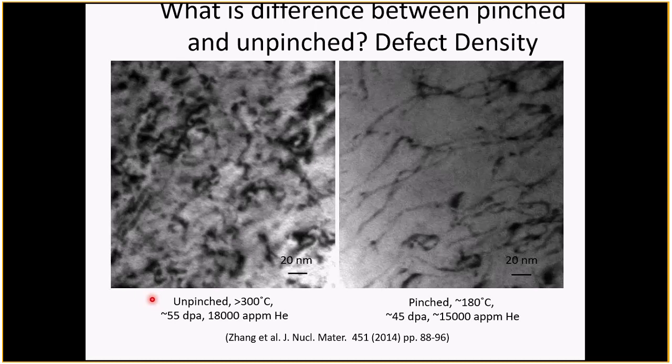You remember in the lecture I gave about diffraction and use of TEM and X-ray diffraction to characterize the microstructure of materials. Well, here's using TEM imaging, TEM diffraction contrast now, to look at the dislocation structure inside the material. Now, the kind of fuzzy areas here are actually the contrast from the cavities, but the darker stuff is actually dislocations and dislocation loops.